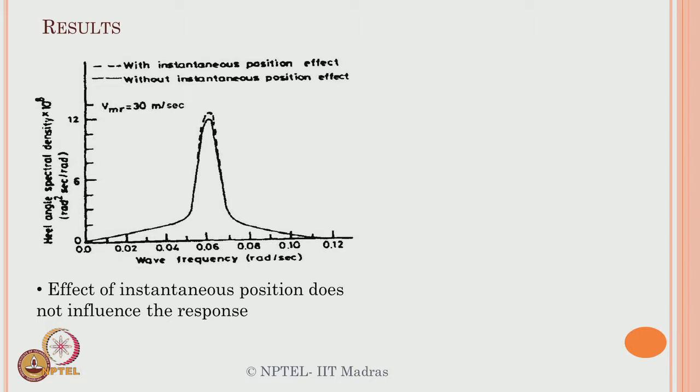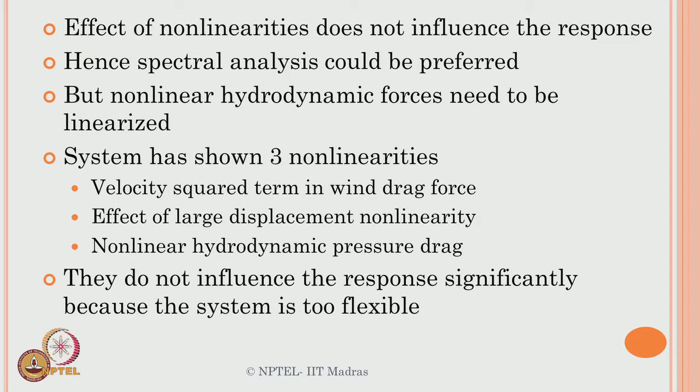So, there are two variations noted here, one is the peak difference, one is the frequency shift. Practically there is no frequency shift at all, it does not affect the frequency content of the result. It of course affects the peak formation, but the variation is not significant. That is what the researchers reported. Therefore, the effect of nonlinearities does not influence the response significantly. One can use spectral analysis. The moment you go to spectral analysis, there is always a static component coming into play here. But of course, the nonlinear hydrodynamic terms need to be linearized, because that is the requirement for comparison.